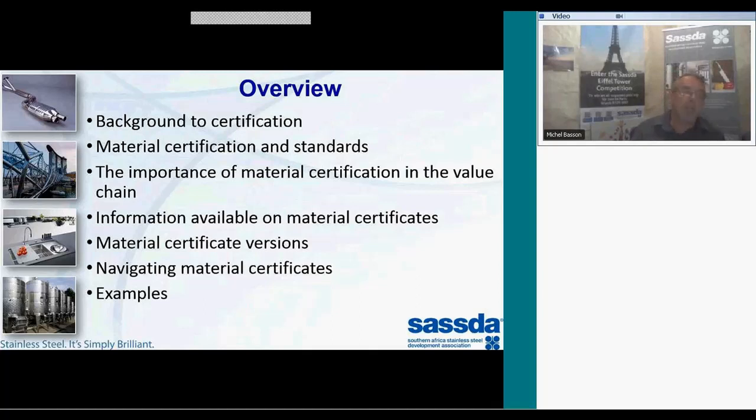This process of verification is driven by a document known as what we all know about the material certificate. Now, material certification becomes an integral part of your quality assurance system, since the material test certificates provide traceability and the assurance to your end user about the quality of the steel and the methods it was actually made by.